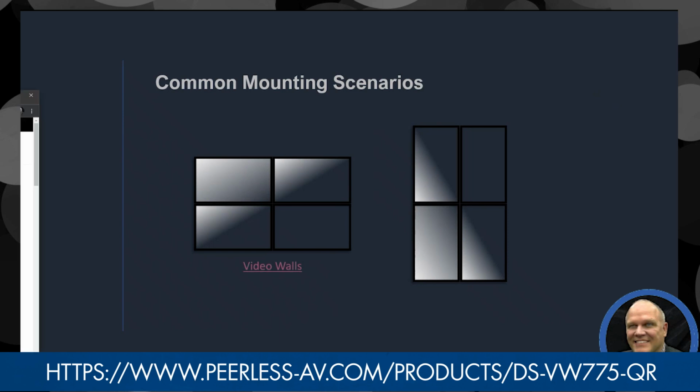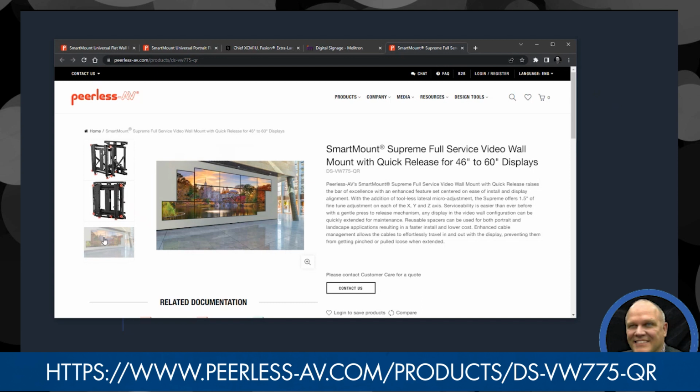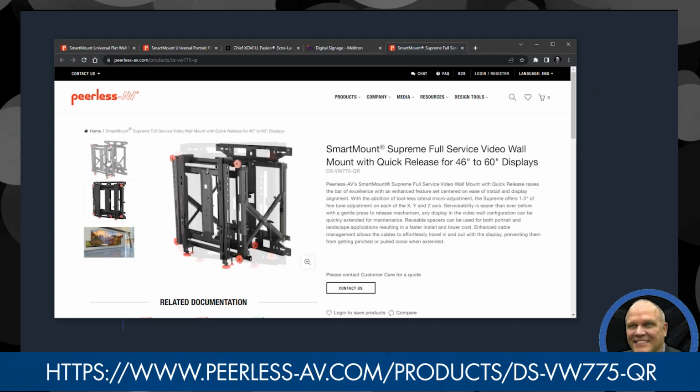A video wall has specific needs, and if we look at the mounting system for that, you can imagine having to create a wall of displays where all of the surfaces are level, flush and equal. That creates some challenges, so you need different types of adjustments. We use these displays. Again, it's a Smart Mount product from Peerless that allows you to pull the displays out from the wall for servicing and connectivity, as well as micro adjusts for getting the overall wall's screen to screen registration perfect. These micro adjusts make that easy and possible.